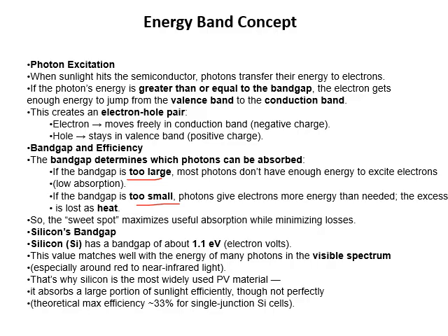Silicon's band gap has a value of 1.1 eV, or 1.1 electron volt. So as long as this 1.1 eV is exceeded, the electron will flow normally outside the solar cell through the circuit, and this value matches well with the energy of many photons in the visible spectrum. So that's why we pick silicon. Number one, it is very readily available in nature, plus the band gap is very suitable for the photons that are coming to the earth from the sun.